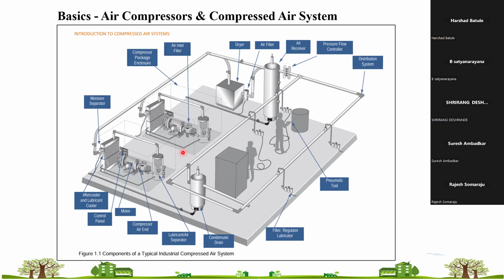And if your compressor has a 0.15, or let's say 0.20 for better calculation, 0.20 as your specific energy consumption, then 0.20 into 13 means roughly 2.6 kilowatt for your leakages. So during your operation, 2.6 kilowatt of energy is being used for your leakages.